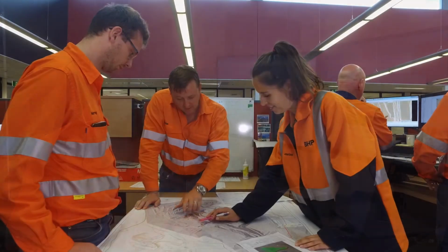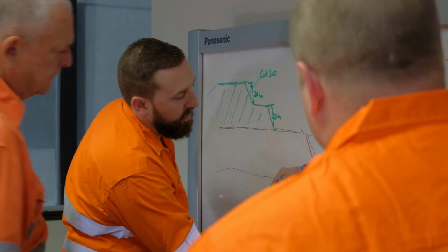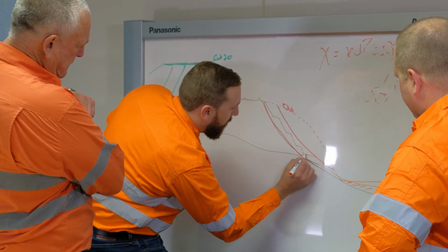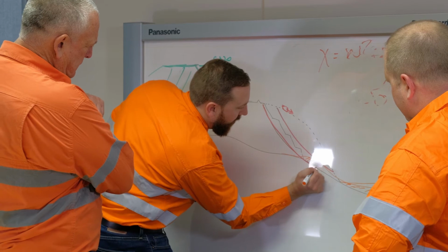Sensitivity analysis may instead be completed where the slope geometry and model inputs such as material strength or ground water level will be varied to determine the change in factor of safety. This determines how sensitive the model is to certain parameters and can reveal what the critical geometry is that may lead to unwanted slope failure. Depending on modelling and sensitivity analysis results, modifications to designs are made to either ensure design acceptance criteria is met or to realise opportunities and increase mining efficiencies.